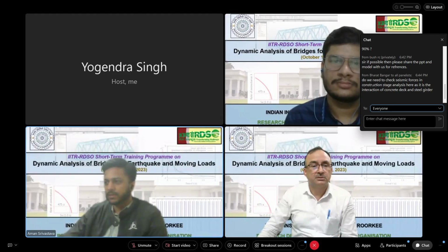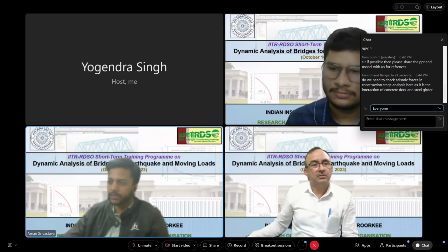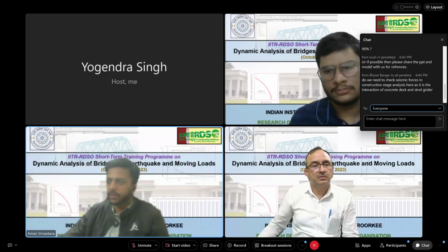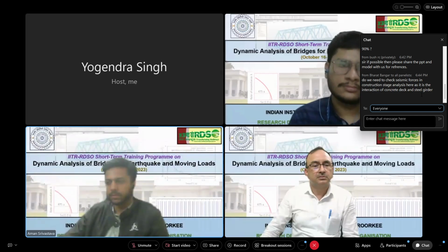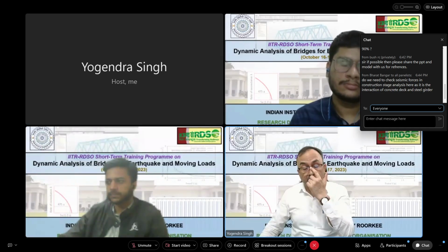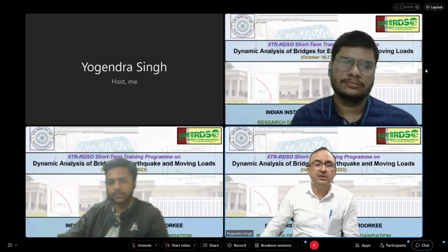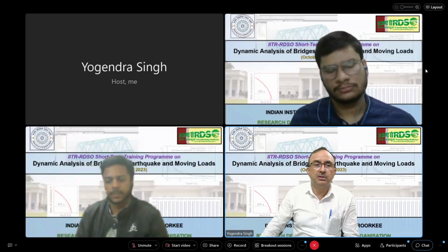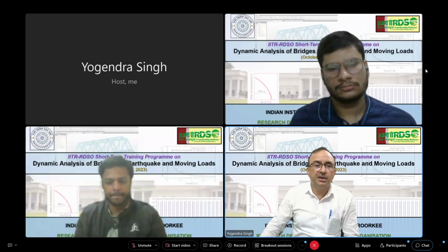Sir Bharat is asking, do we need to check seismic forces in construction stage analysis here, as it is the interaction of concrete deck and steel girder? Yes, so the codes provide the load factors. So we consider a lower level of earthquake during the construction. So we can take as per the relevant code.